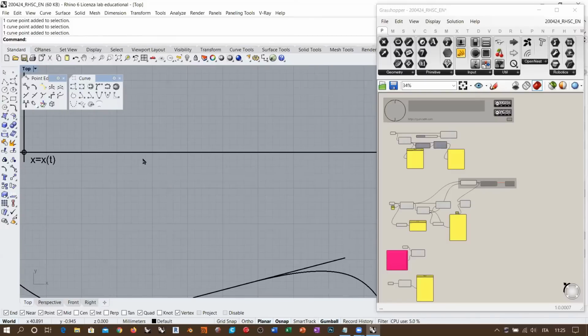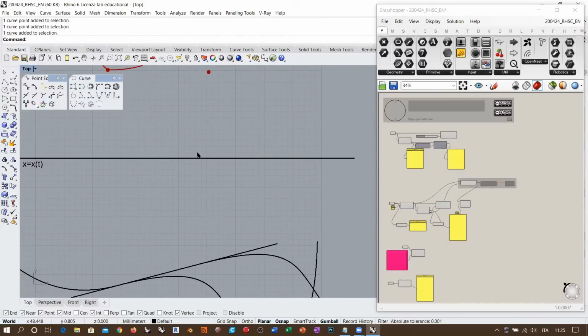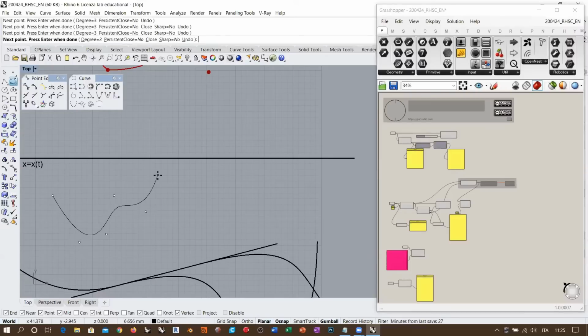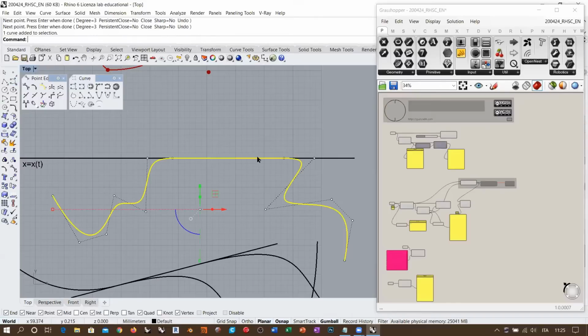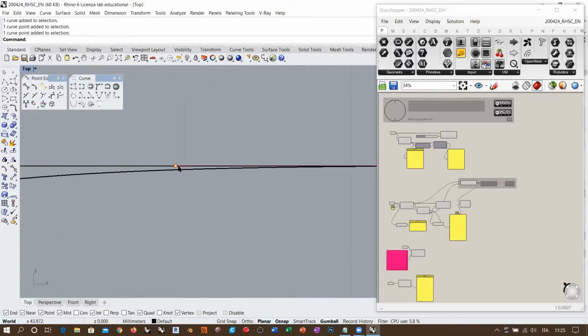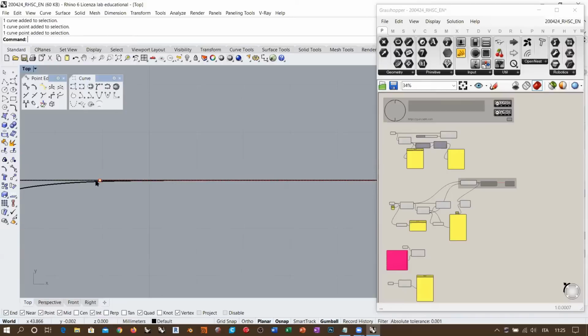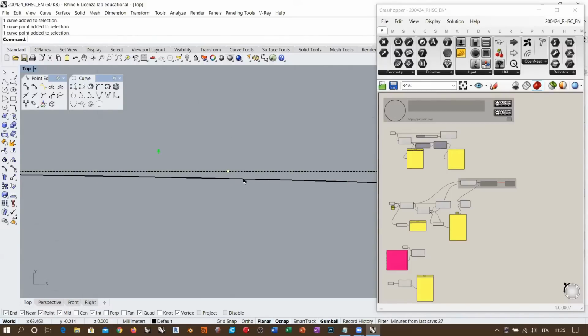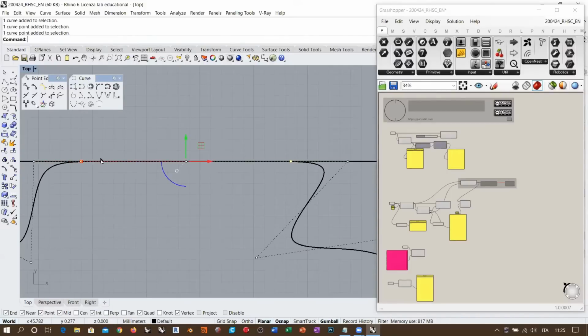So you can see that, for example, if I have this straight line here as a reference, I can draw whatever I want, and then place 1, 2, and then 3 and 4 control points, and you see that my line is actually having a whole section which is totally flat. Where is this flat section starting and ending? It is not starting in the control points that are between this set of 4. As you go closer, you see that there is separation here, and there is also separation here between the lines. It is starting in the corresponding knots.